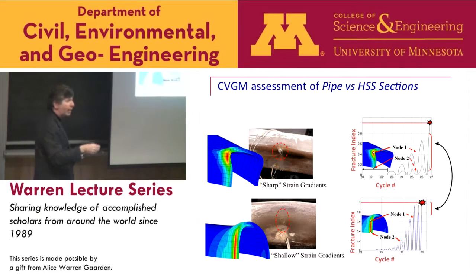And of course, from finite elements too, we know that you can get the overall behavior pretty well with finite elements, but the local behavior might not be captured as well. Okay, so we have to worry about paying attention to our cyclic model, our mesh size, the geometric imperfections, and so forth to get an accurate measure of the local buckling and the strains, and then putting that